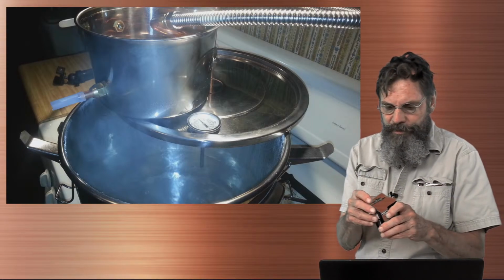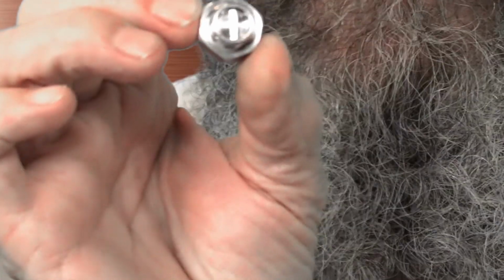And this is an important thing that I want to mention here. This is a pressure relief valve that they use in pressure cookers. It's just a safety valve. So if there's too much pressure, I'll just take it out and show it. It's only a little teeny thing, and it's easily mounted by drilling a hole. It's very small. You can see that it has a hole in the bottom and a screw mount. So you unscrew the screw, put it through, drill a hole in the lid, and screw the screw back up. It has two seals that go with it. So essentially, that fits into the lid of the vessel.